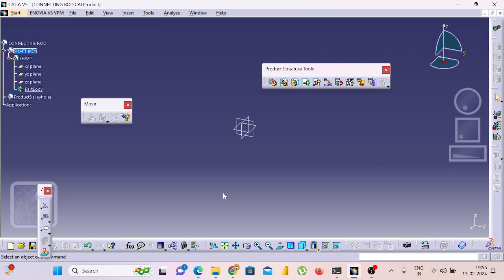Next, there is a fix command in the manipulator only. When fixing one component, it cannot be moved in that direction; it will be fixed in one direction only. If you want to see which direction we have fixed, there are 6 degrees of freedom. 5 degrees it can be moved, 1 degree is locked. These are the few commands that I explained today in assembly.